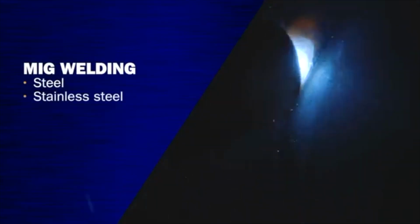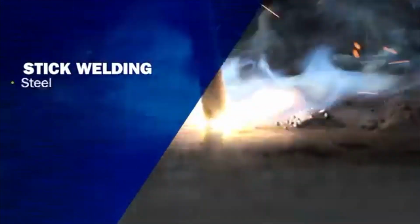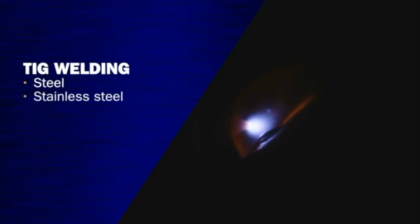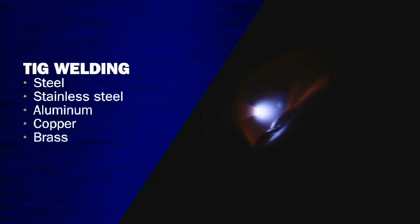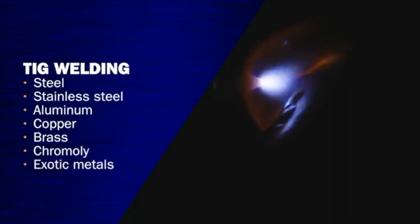Now let's get a little bit more specific about what metals you can use for each process. MIG will typically weld steel, stainless steel, and aluminum alloys. Stick can weld steel, stainless steel, and cast iron. Whereas TIG pretty much runs the gamut. You can weld any metals that conduct electricity: steel, stainless steel, aluminum, copper, brass, chromoly, and exotic metals such as magnesium and titanium.